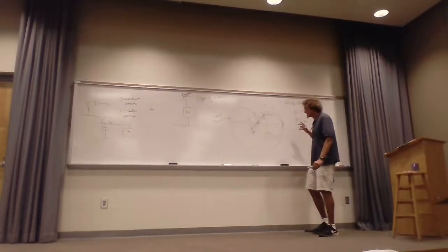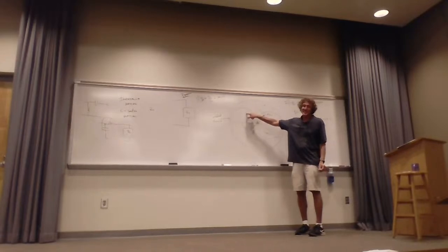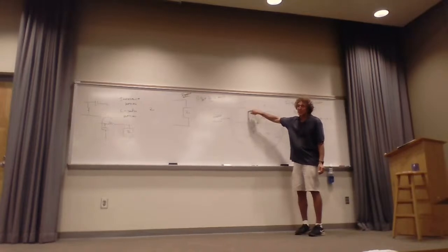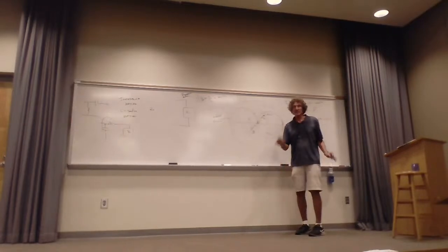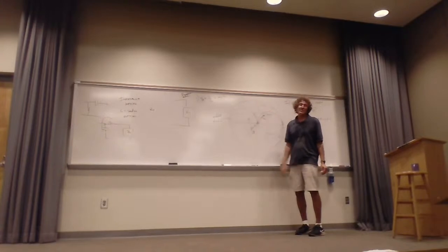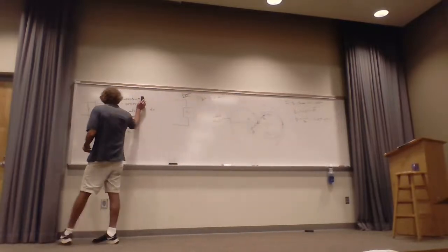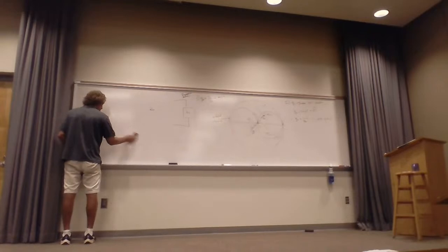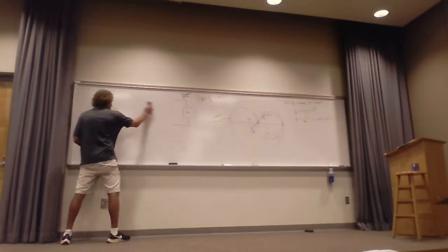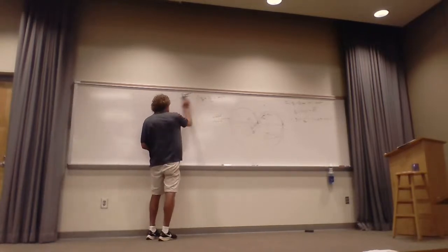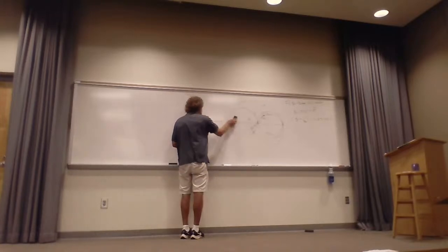Now, if the initial point is outside the 1 circle, then the first thing you do is, in the rotated, I'll go through this one in a bit. You add an impedance, get to this point, and go over here, and then add an admittance. But I'll do this one, just so you see the process. If it's outside of either of those, it doesn't matter what you do. And I'll show you that one too. So this is real microwave engineering. Now we're gonna do the actual problem. And I gotta show you how to get the normalized value of the capacitance and inductance.